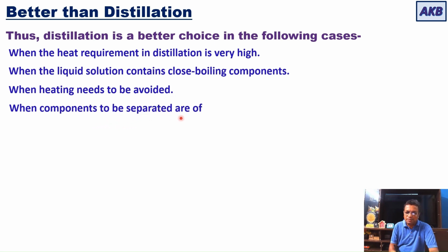When components to be separated are of quite different nature. So if components to be separated are of quite different natures, then also you can choose liquid extraction over distillation. So these are the applications where you can say that liquid extraction is a better choice: when heat requirement in distillation is very high, when the liquid solution contains close boiling components, when heating needs to be avoided, as in the case of heat sensitive components, and when the components to be separated are of quite different nature.